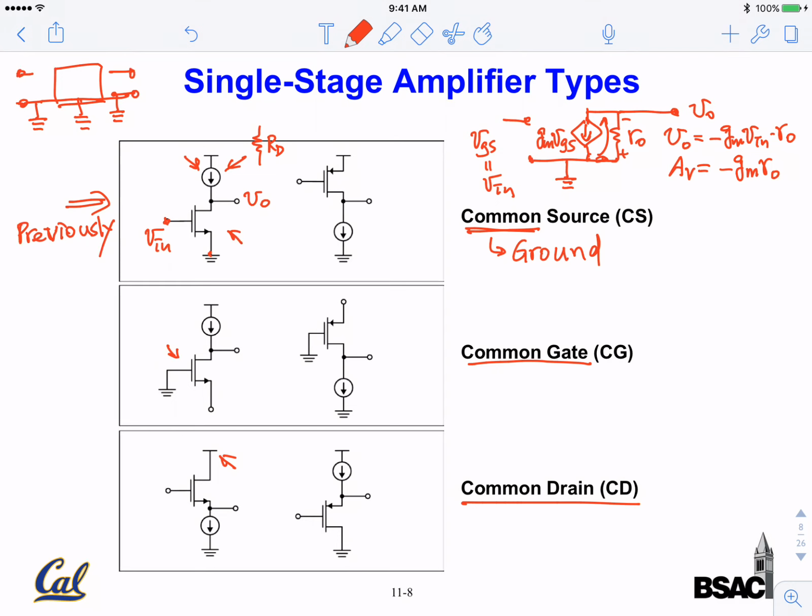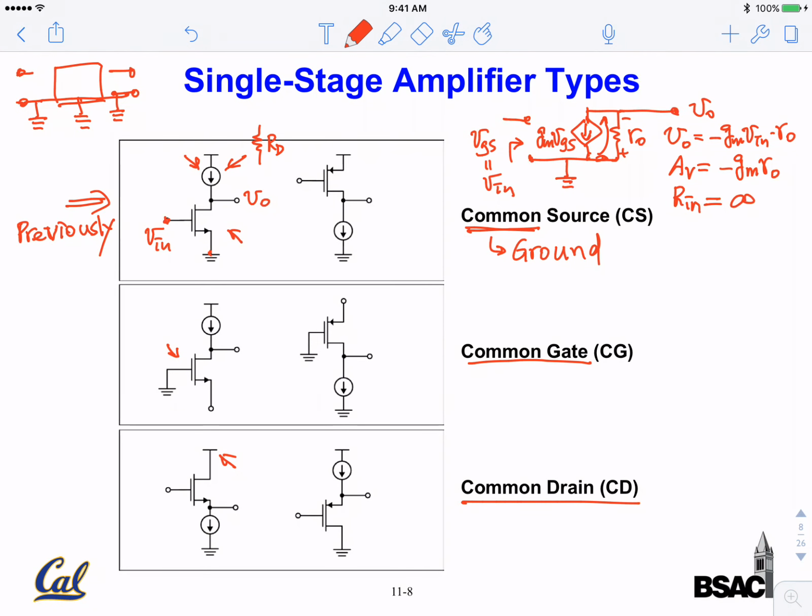We also care about input resistance. Input resistance, R in: you are looking into the gate. You're looking in here, okay? So it's an open circuit. It doesn't matter whether we attach RL or not. So the input resistance is infinity, okay?